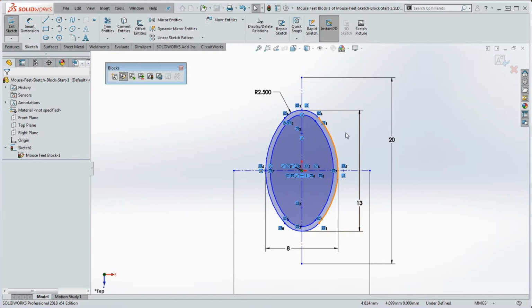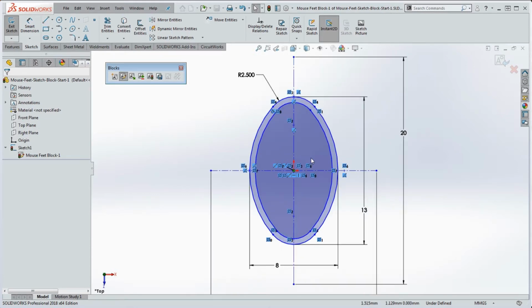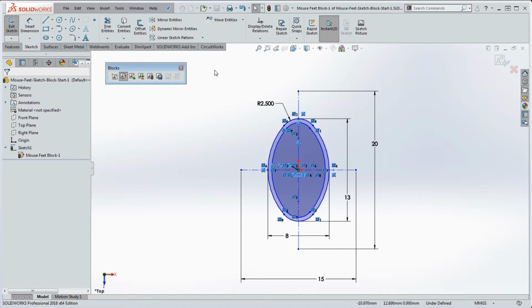One thing to keep in mind when you create blocks like this, you want to get rid of a lot of your horizontal and vertical sketch relationships that you had in here before, as best you can. Because if you were to take that block and rotate it around and then explode that block later inside of another sketch, inside of another feature, inside of another part, that could be troublesome. If this line were initially horizontal and then is suddenly in an orientation that was not horizontal, you're going to have an error there you might have to correct. So we're going to take a look at some of these sketch relationships a little bit later. When you do create blocks like this, a lot of times those sketch relationships that were in there before get deleted. But we're going to show you some ways to get around that here in just a moment.